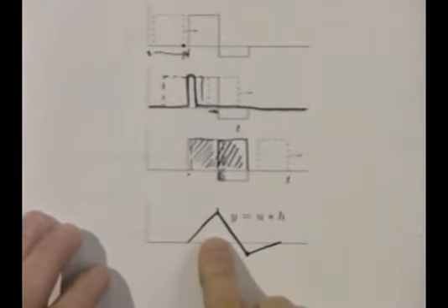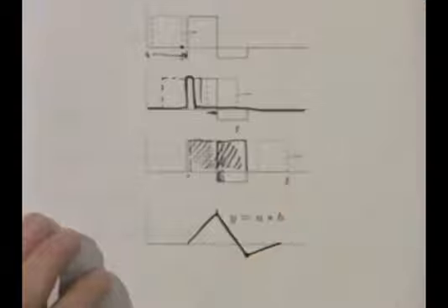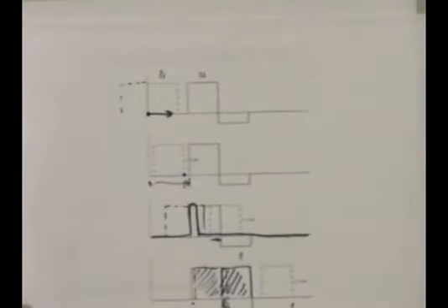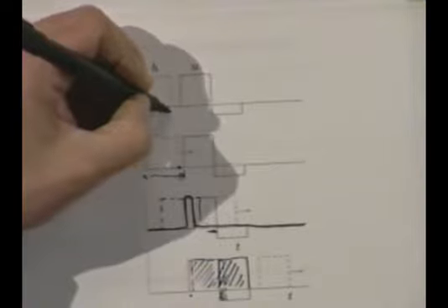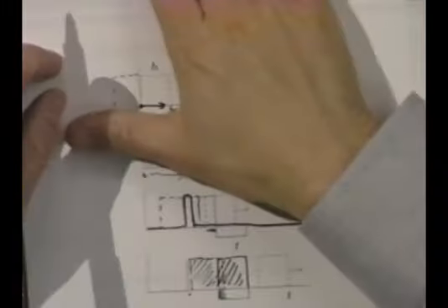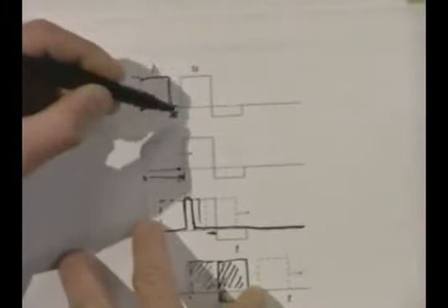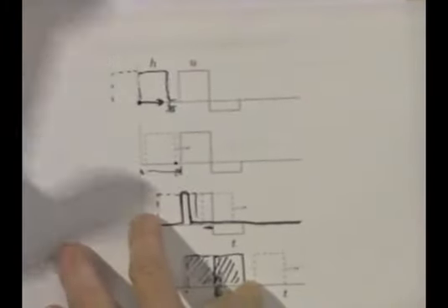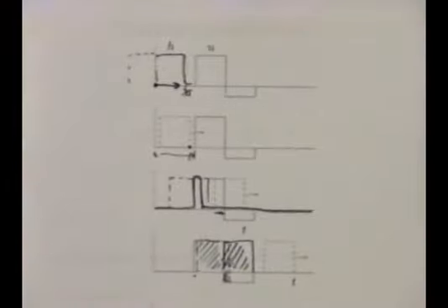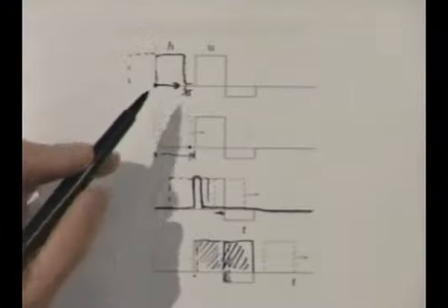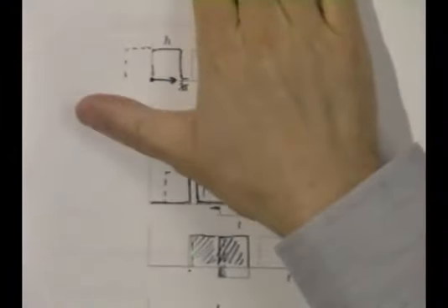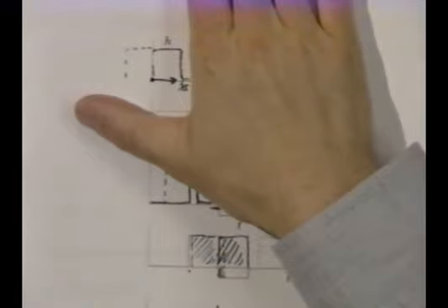Now, we can also understand this result by looking back at the previous interpretation. Let me put some numbers on here. Let's call that 0.75 seconds right there. So if I just came up to you and said, I have a system, and its impulse response is this function right here. It's 1 for 0.75 seconds, and it's 0. How would you describe in words what that system does? Just informally. What is the output at a given time? That's its impulse response. Just that.